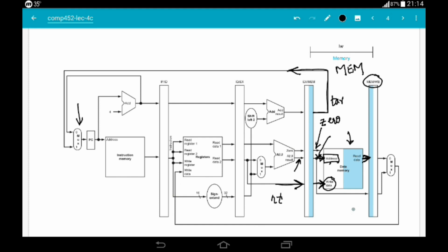And look here that this value, in the case of load word instruction, this is also the address, so it is also coming here. So we have the data here and the address from where the data is being read here, but this value will not be forwarded in the next stage because we want to forward this read data.